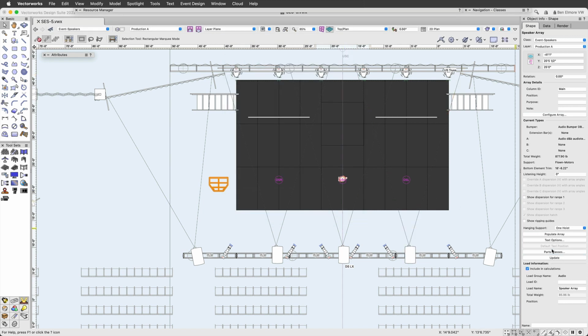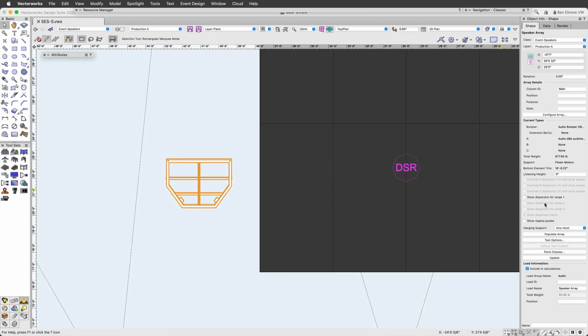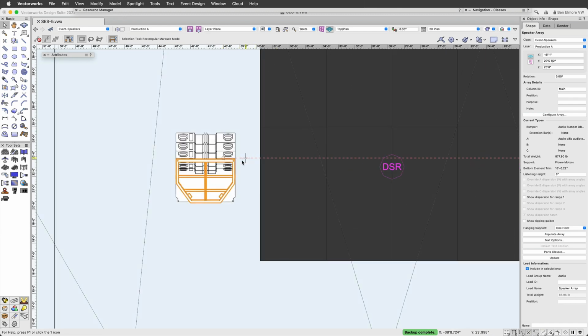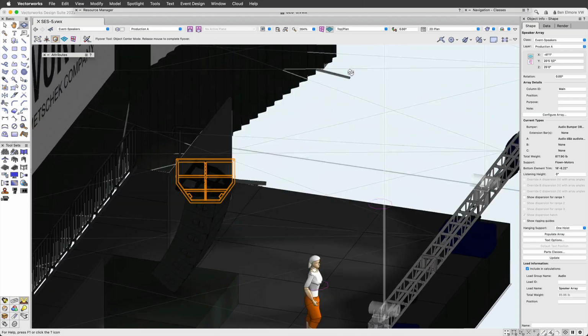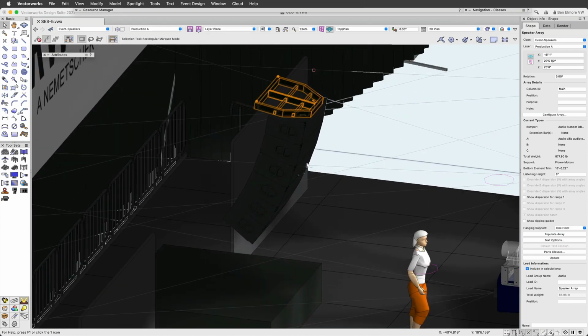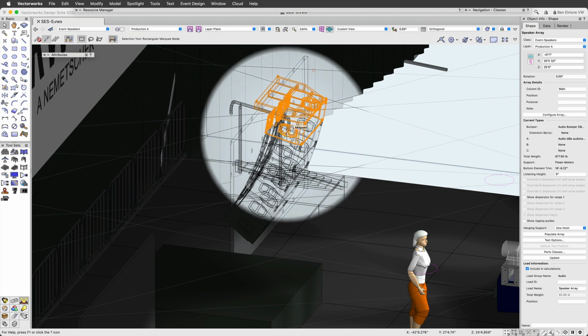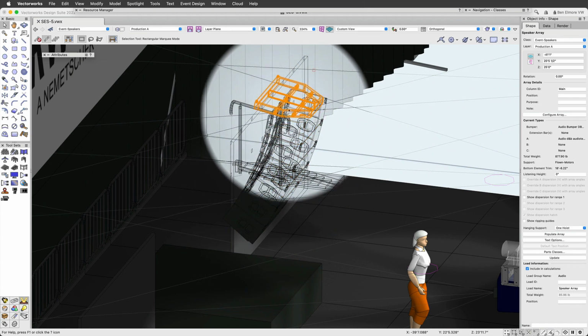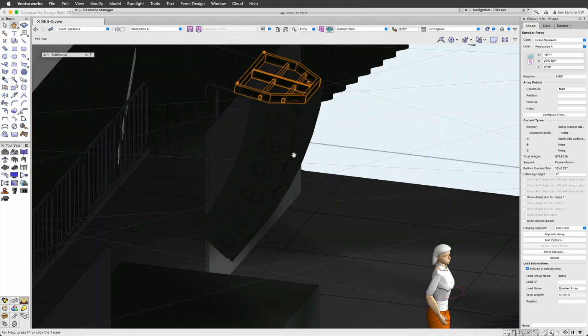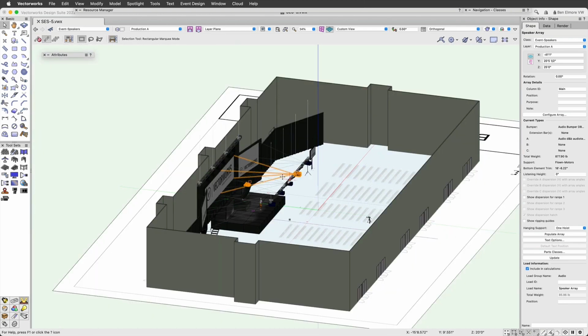And then the last thing that we need to do is just hit this populate array button. You'll see that currently there's just a frame sitting on the drawing. So hitting this will pull in all those angles that we set and the overall bumper angle and populate that array based on those settings. You'll see if I go up to a 3D view, it's got the right angles. I'll use my X-ray mode with the B key. You'll see it drew 6 little symbols in there at the correct angle with the overall array at the correct height. And I'll just mirror that.